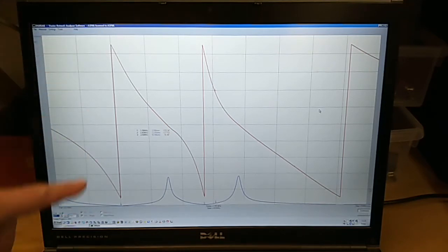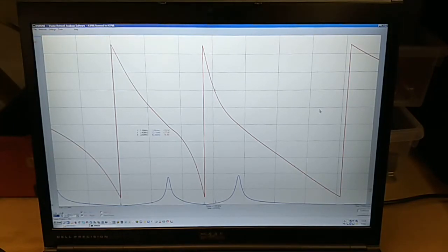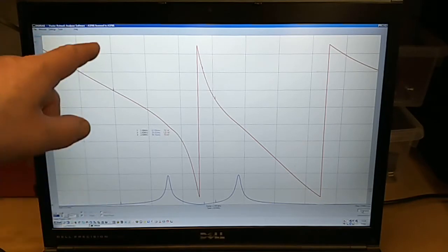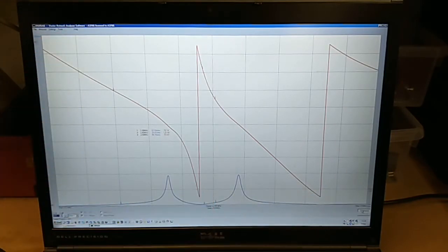We also now have this here. If I take out the tank capacitors, we will see that disappear. I'll just pause for a second. I've taken out the tank capacitors. We'll rescan that, and we see this phase change has gone. Slight shift of the other points as well, because of the interaction effect of that peak.